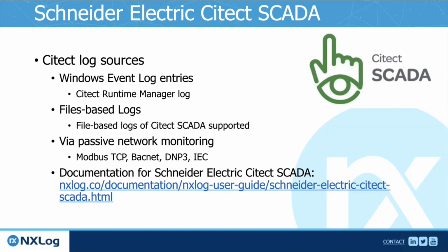So here, Citect SCADA simply leaves a lot of useful information in the Windows event log. File-based logs, there's a whole list of Citect SCADA parts which create some sort of file-based logs, and this also can be used in building a log collection pipeline.